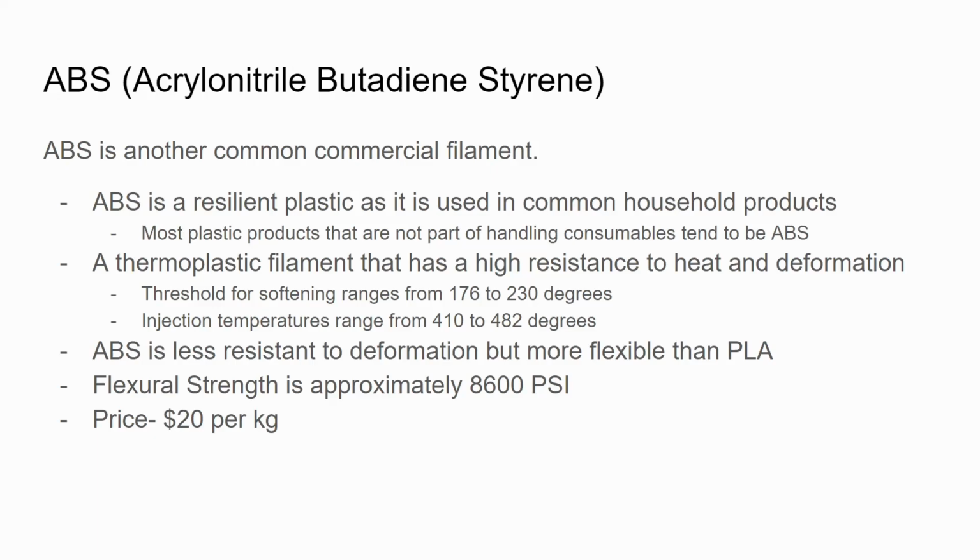The issue with ABS plastic is that it's very sensitive, and you need to find the exact temperatures and speed and settings that work for your printer, or else instead of getting a messed up print, you won't get a good print at all, where the layering won't work in the way you want it to. So instead of warping or being loose, it doesn't layer at all and creates this spaghetti strand mess of plastic. So you need to make sure that when you use ABS, you have to find the correct settings that work for your printer.